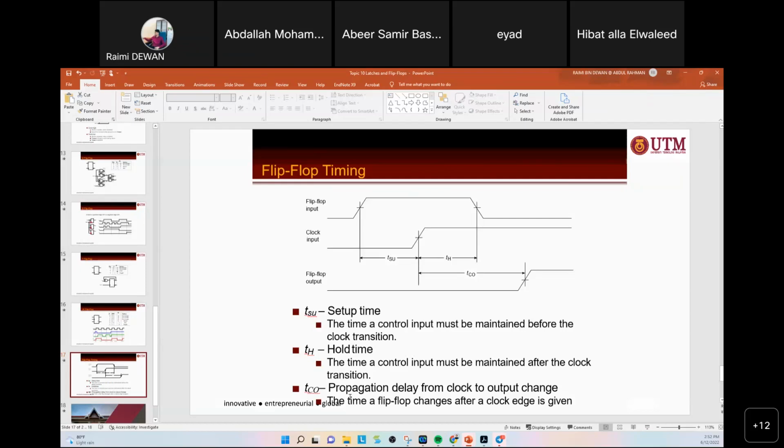What is the duty cycle? It's easy. Duty cycle is the active state over the total time. And the frequency of the signal is 1 over T, the complete period of one duration. So one duration is 200 nanoseconds plus 300 nanoseconds for question 10.9. So this one is quite direct.